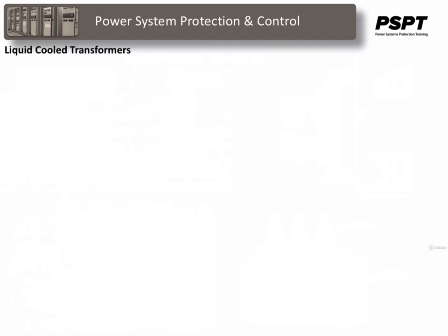Liquid cooled transformers cooling classes went through a major change in the United States when the IEEE standard C57.12.00-2000 adopted the four-letter designation found on modern power transformers. These four letters, usually found on the nameplate and or on the drawings or somewhere describing the cooling system of that particular transformer. And the four-letter designation is described in this manner.